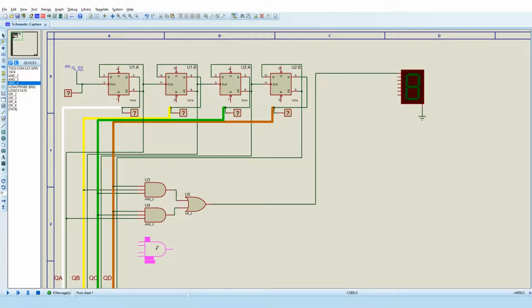Now we're going to do segment B, which was two 4-term AND expressions and an OR gate, because it was D not C, B not A, or DC not B A. So we'll wire that up. I've added some text labels. The little capital A on the left hand toolbar, just click that, and I added some text for the wires.